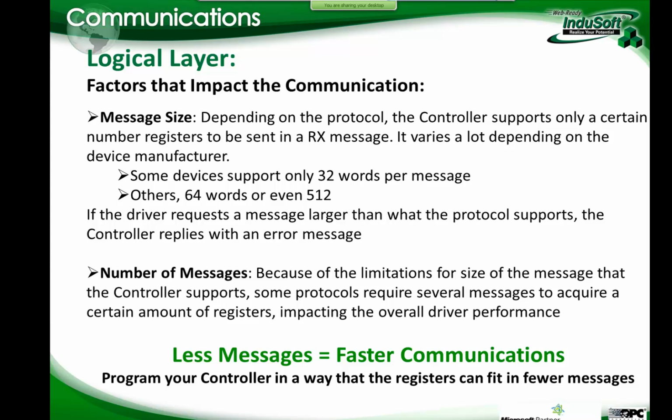And so every time we want to know what is on the PLC, we're going to prepare a message in the format that we showed on the previous slides and send those messages to the PLC. The PLC will prepare the answer and send it to me. And how much information is going to be in that message will depend on which protocol we are using. The more modern the protocol, the more bytes you have per message. And the fewer messages you exchange, the faster your communication is.